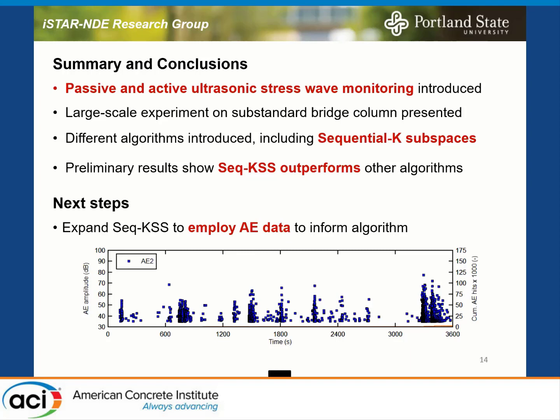Here, I'm just zooming in on the very beginning. I'm not showing the loading here, but at this point, that's the first time we introduced cracking in the column, at least cracking that we were able to observe, I should say. That's always the problem. Acoustic emission is also pretty sensitive, so you might miss the first ones. But each time you have a little cluster of acoustic emission hits, some internal fracture occurred that you picked up. That's where we're at, and that's all I have.